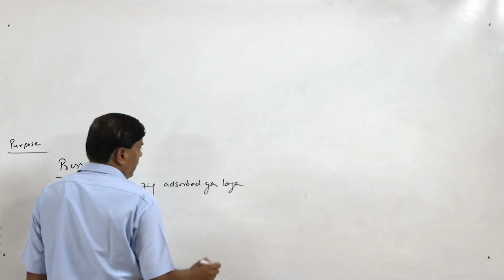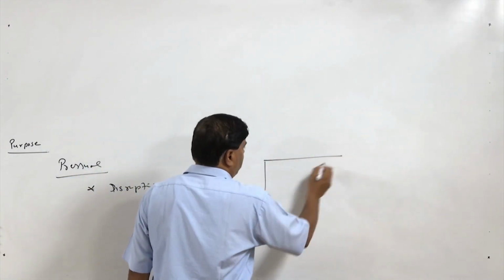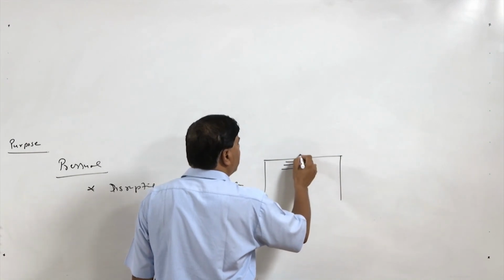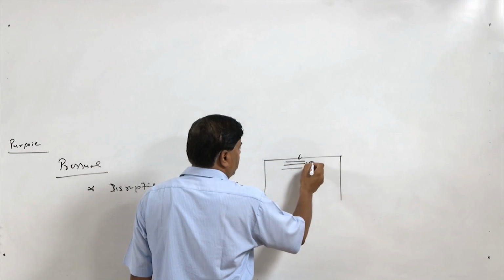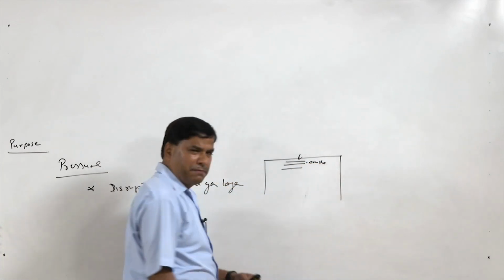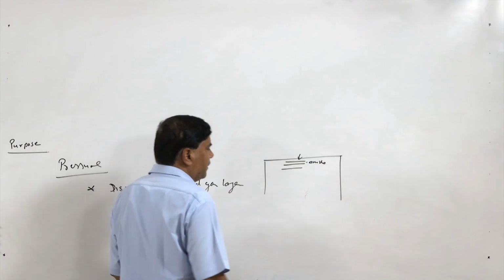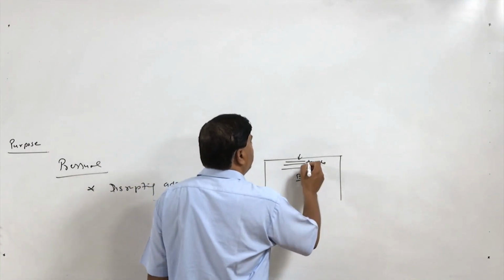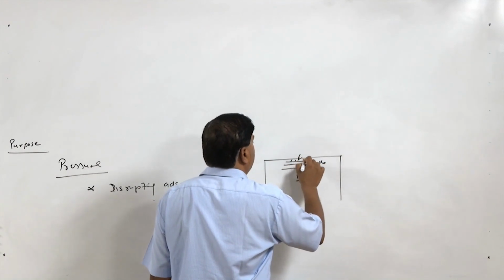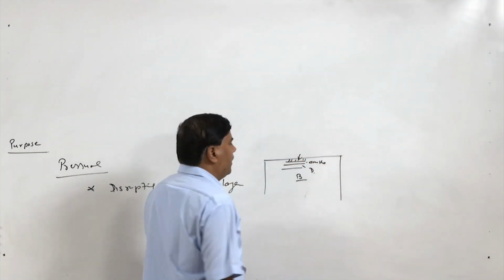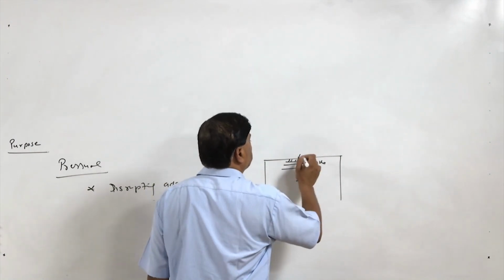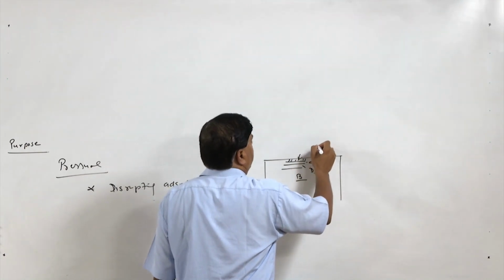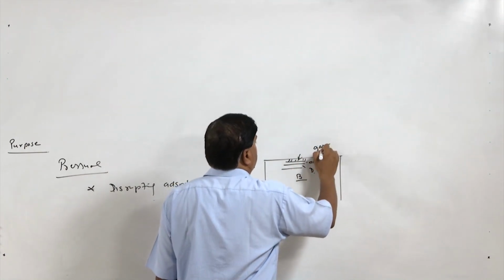We know that all the real components are made of a number of layers: this is the bulk, this is the deformed layer, then the oxide layer, and then the adsorbed gas layer. The thickness of these layers may be at the nano level or at the micron level. The surface at the very top, a very few nanometers, has gases adsorbed from the atmosphere.